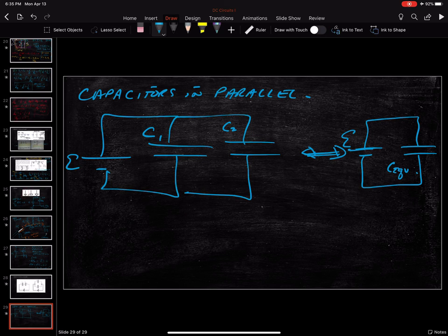So what do I have? Well, this voltage is pushing out some charge. It's putting out some current, and that means that you build up some charge, say positive Q, on this top plate of the capacitor, and negative charge Q on the bottom plate. And so the change in voltage across that equivalent capacitor is Q over C. It's the charge on the plate divided by C equivalent.